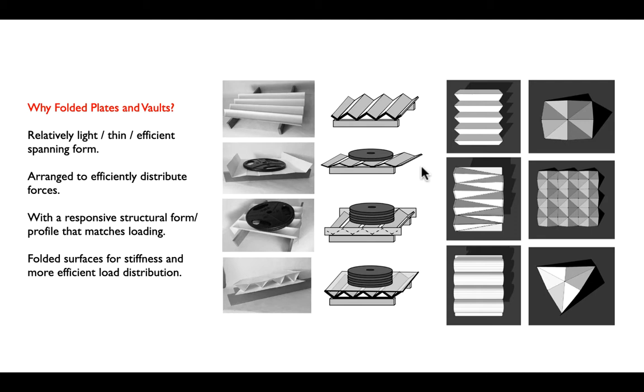When we design a folded plate, we're usually designing some kind of roof. We're usually taking a section active principle and trying to stretch it out to also being an enclosure. And what we want is to get a vertical separation between the high points of the fold and the low points of the fold. And what that does is it takes that thin plate and gives it the section modulus of a much, much deeper beam, right?